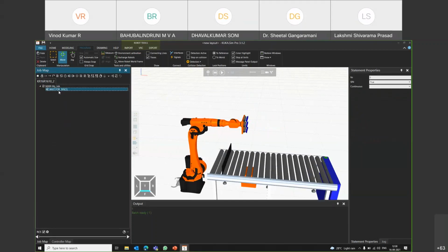What they do is they put different kinds of wait signals or different kinds of output signals. An output signal is used for picking up the component. Let me say my wait for 100 to be true. So what does this 100 to be true refer to? Once a component is available in the picking area, my input number 100 will be high.